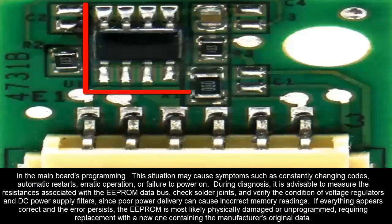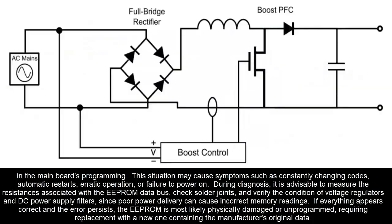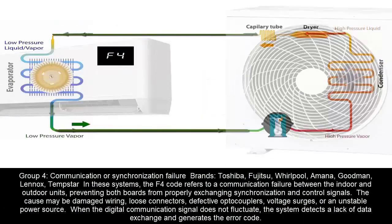During diagnosis, it is advisable to measure the resistances associated with the EEPROM data bus, check solder joints, and verify the condition of voltage regulators and DC power supply filters, since poor power delivery can cause incorrect memory readings. If everything appears correct and the error persists, the EEPROM is most likely physically damaged or unprogrammed, requiring replacement with a new one containing the manufacturer's original data.